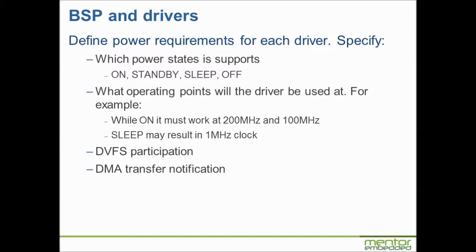Actually, that would be a good name for a low power mode, the siesta mode. That would be quite good, wouldn't it? Well, that would be okay, but the DMA transfer is still carrying on. And if you reduce the frequency of the CPU, that's going to affect the frequency of the bus and hence the transfer, and potentially it could mess things up comprehensively. Broadly speaking, though, the driver needs to be able to indicate to the CPU that it does DMA transfers, and therefore, please don't pull the plug on me while I'm transferring data, is the gist of it. I quite like siesta mode. I must write about that.